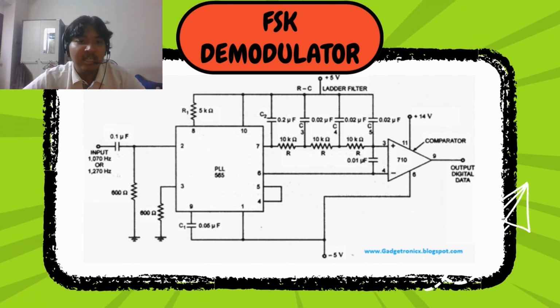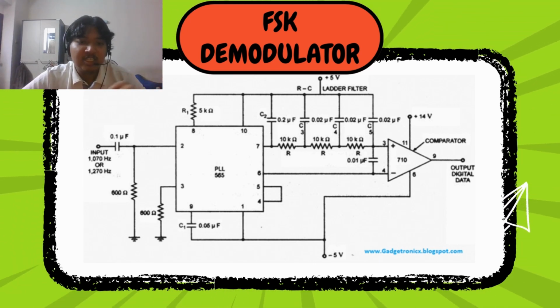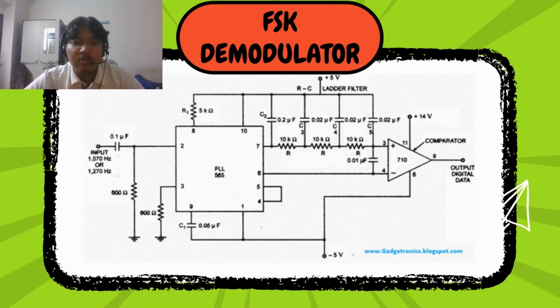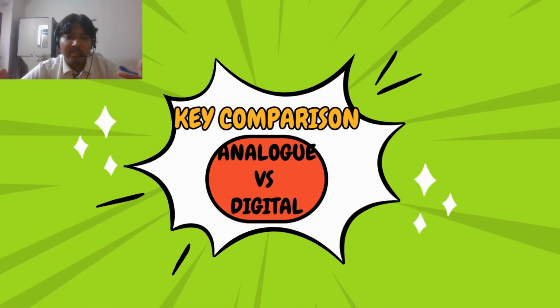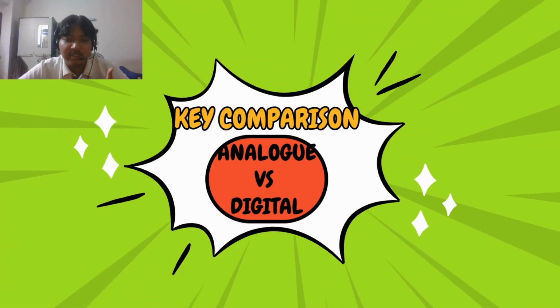It can be achieved by applying the coherent detection method or the delay detection method in the FSK demodulator circuit. In this case, we're using the delay detection method. The delay detection method can use the time delay between different frequencies in the received data to get the original digital data signal back. Let's compare and analyze the difference between analog and digital modulation to evaluate these factors: bandwidth efficiency, noise resistance, complexity of circuit design, and practical application.